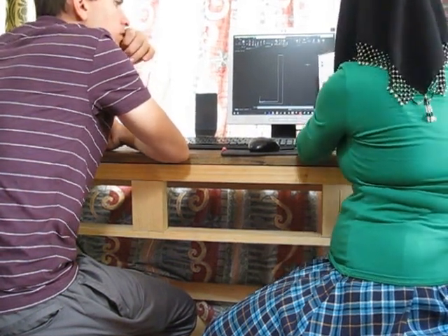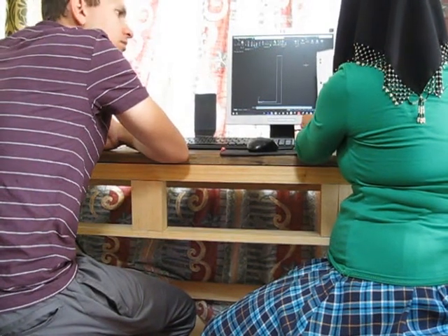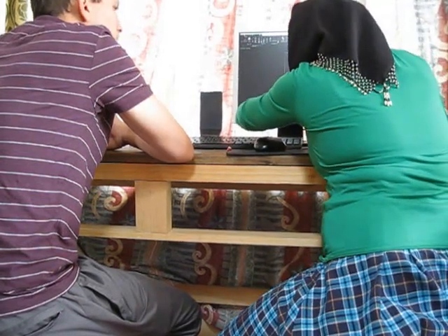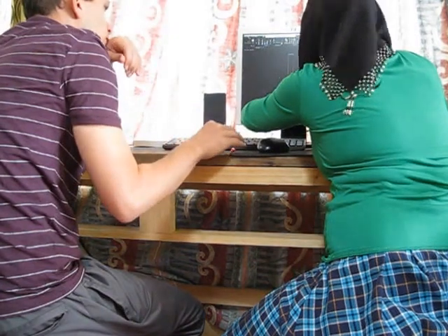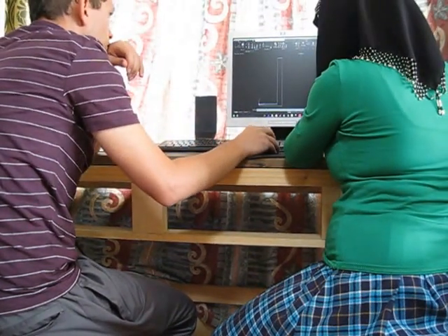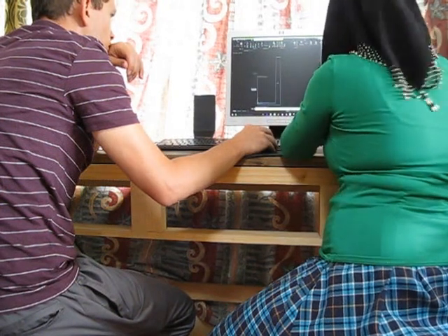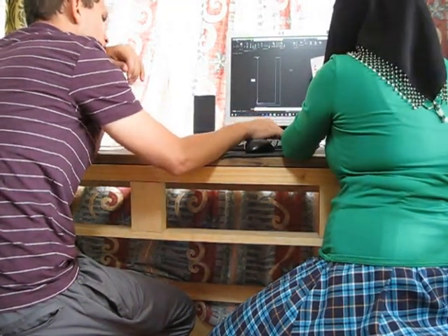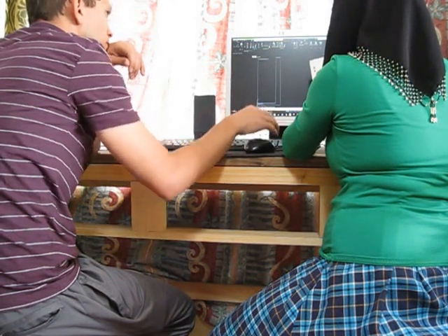Okay. So we have to go with this line. How far is this line? This line is 2490 from the bottom. So because we have already drawn a little bit of it, go on here, the top of that corner, here in this corner, click, and go up 2400 to reach the ceiling, and click. Right?